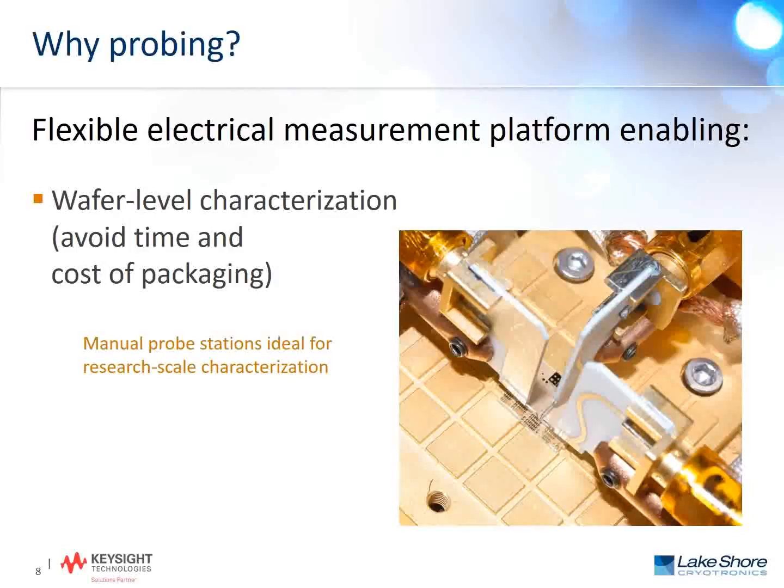That includes dicing your wafer, wire bonding to the device pads, mounting the device in a package, and then finally, in the case of cryogenic characterization, cooling the device down. There are a lot of steps and a lot of time and cost added by packaging devices. Probe stations allow you to get around that, and basically make temporary electrical contacts to a wafer level device.